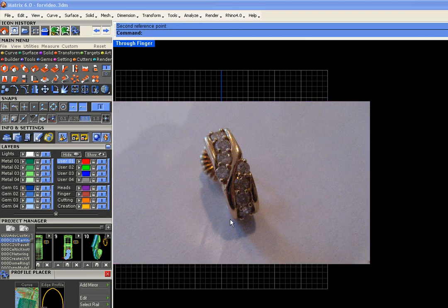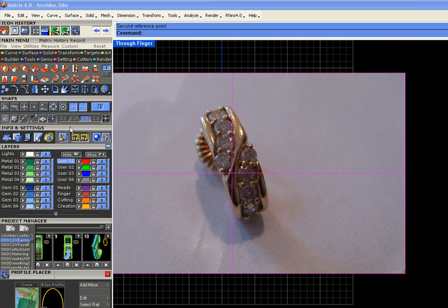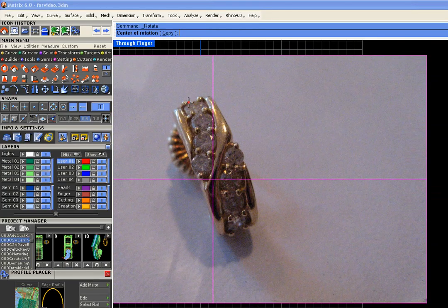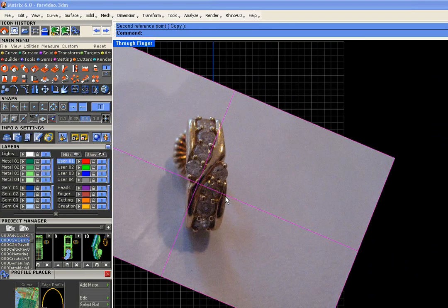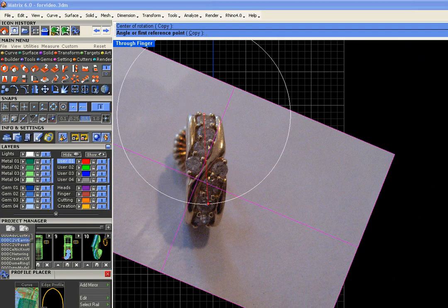The other great thing is you can rotate this surface. So we can see how this is all at a weird angle, we can get it at the right angle. So rotate, select the surface and click rotate, and then draw a straight line through the model and shift to rotate it down straight. And if you didn't get it quite right the first time, it's very forgiving.